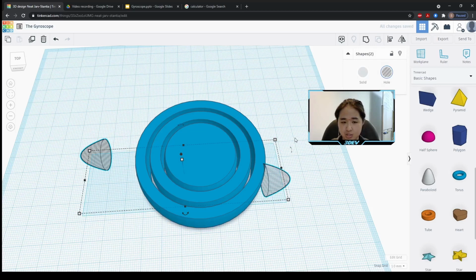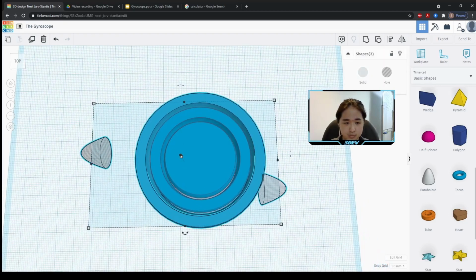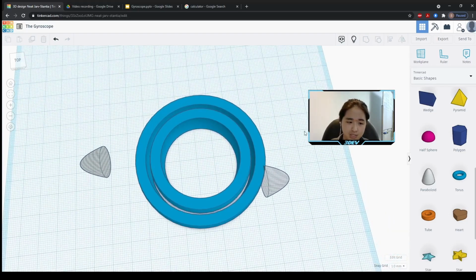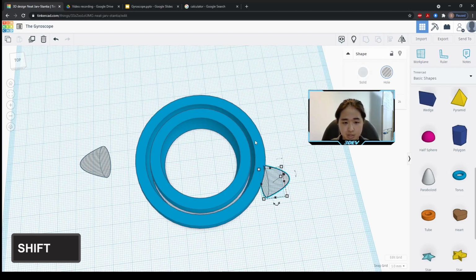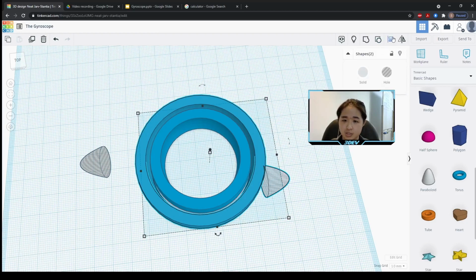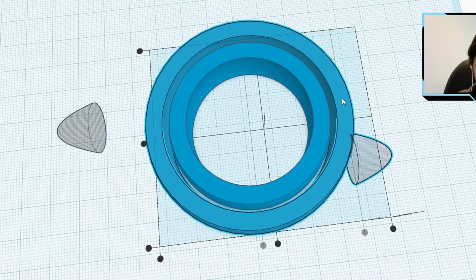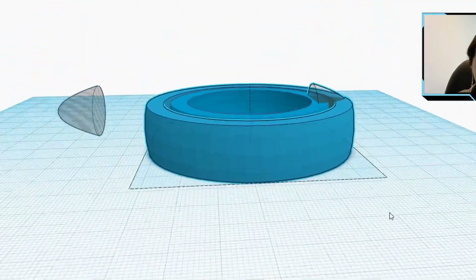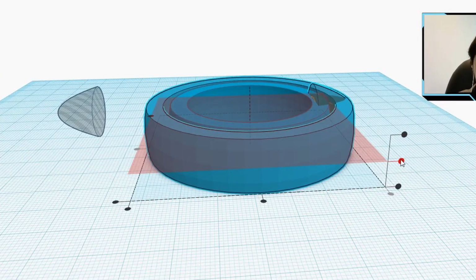So I'm going to click this tool and click on my outer gimbal, the first one. So hold shift, click on it. Maybe I hide this one for you guys. Good, now we can see better. So I click on this, hold shift, click on the first gimbal, and I press align. Click on the gimbal again, so that the gimbal won't move, only the paraboloid. I'm going to change this one to the center, this one to the side, and the z-axis also to the center.